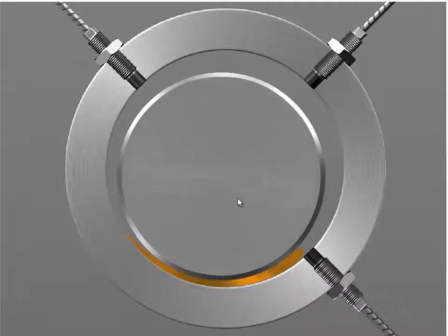So here is what's happening inside these machines. You've got the journal bearing itself. There's the bearing part with the special metal, and here's the shaft, or where it is inside the bearing, we call it the journal. So sitting underneath this is a wedge of oil that forms. We pump the oil in, that keeps it supported, keeps it stable, keeps it cool, all sorts of good stuff. But unfortunately, if we've got some unbalance or whatever is causing the shaft to move, that vibration doesn't transmit well through the oil out to the bearing, and so therefore an accelerometer may not pick up what's going on.